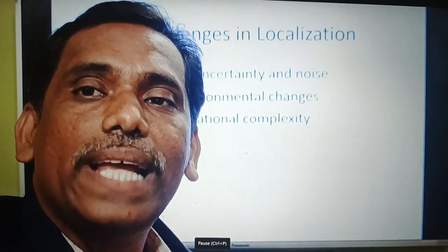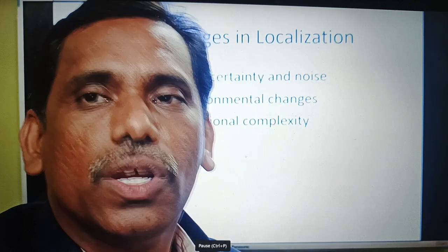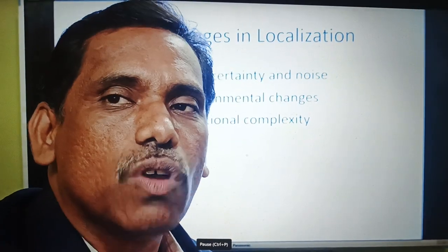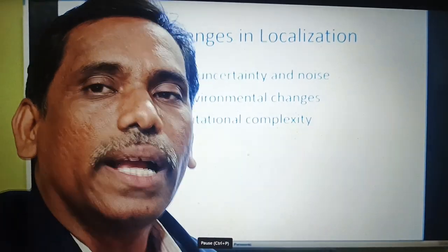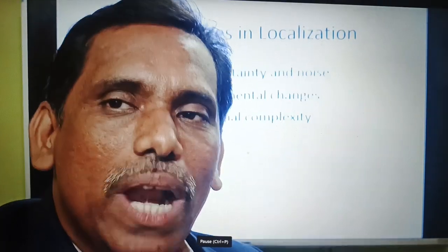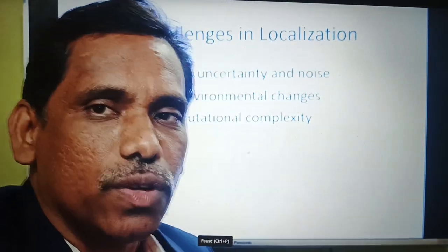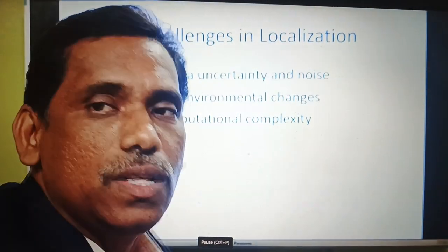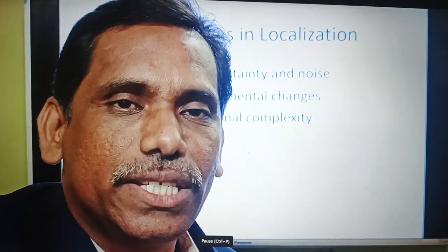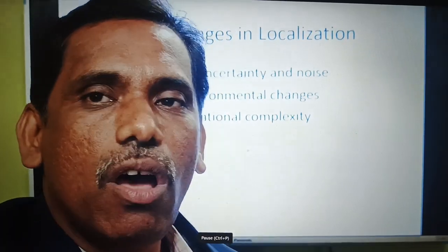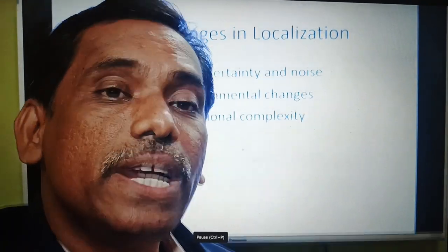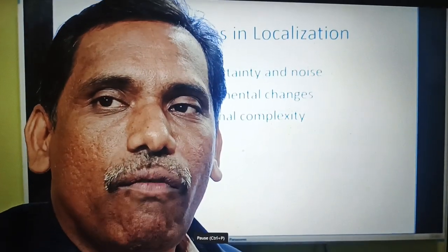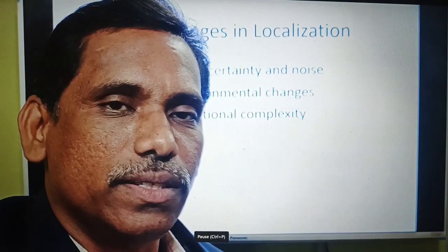Sensor limitations: GPS signals can be blocked indoors or in tunnels. Cameras struggle in low light or foggy conditions. Accumulation of errors: small errors in position estimates add up over time. Odometry often suffers from accumulative inaccuracies.